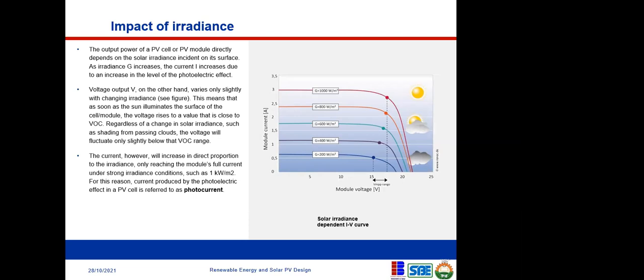So the current is not the same. However, sorry, before you leave the voltage, typically do your solar cells come in different voltages, or are they all produced at a particular voltage? When you look at the label on your solar panel, you will see the voltage. They all have their operating voltages. So different solar panels come with different voltages? Yes, it's possible. Typically 12, 24, 48. You can string them together too, to get the required voltage that you want.